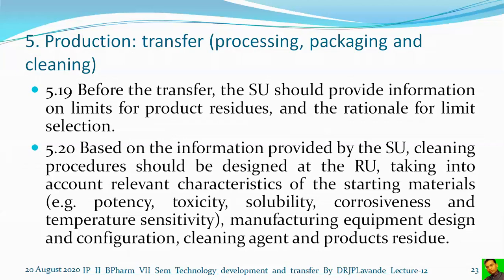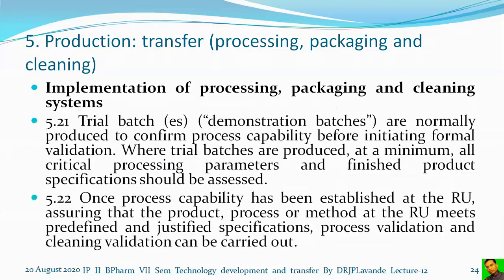Now, these characteristics might be, for example, the potency, toxicity, solubility, corrosiveness, and temperature sensitivity. The manufacturing equipment design and configuration, cleaning agent, and product residues.